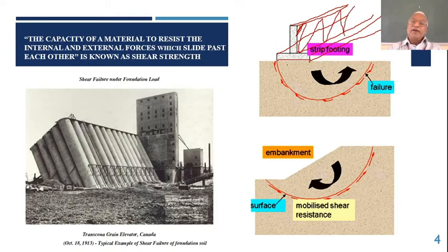Now anyway, it has collapsed here on the left hand side. It has gone down, right, pushing the material over here. So what happens is there will be a slight bulge on this side, may be observed, may not be observed, but this will be shearing along this particular surface, right? It has sheared and then failed. The opposite side arrows show resistance. These arrows, which act on this curved surface, are nothing but shear stresses. The resistance offered is given by the opposite arrows. These are applied shear stresses, and then the failure has occurred there. Okay, this is foundation failure.